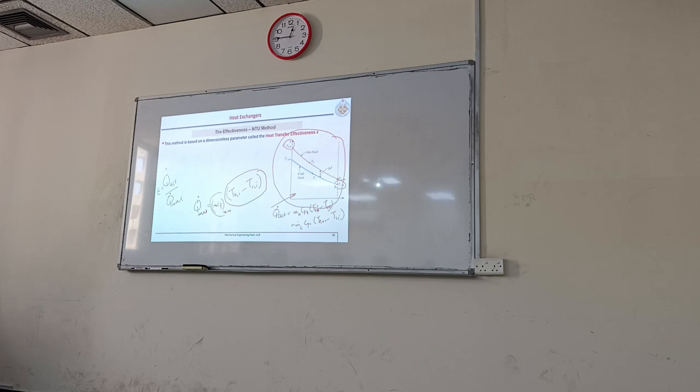Whichever is minimum, that is actually defining the maximum temperature change. The minimum MCP product is the bottleneck, or the threshold, or yeah, many terms like this. Limiting factor. So whichever MCP is smaller, that must be multiplied here.